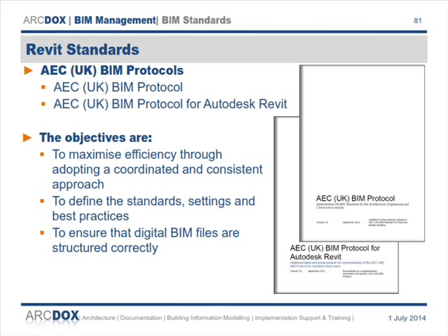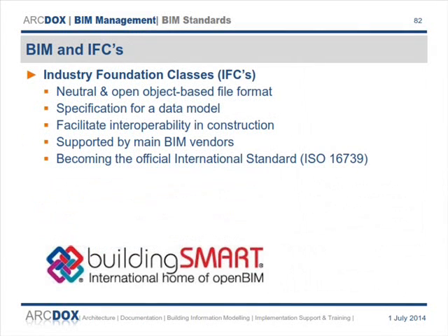Yeah. Again, if everybody's working in the same file format, that's great. You get your files and you share them. If you're working in different software packages, that becomes a little bit more of a challenge, but Building Smart have the IFC, or Industry Foundation Class, which most software packages can export to and import from. Okay, it's a neutral file format for BIM information. So you can export from Revit to IFC and you can import IFC into Revit. Most packages can do the same thing.